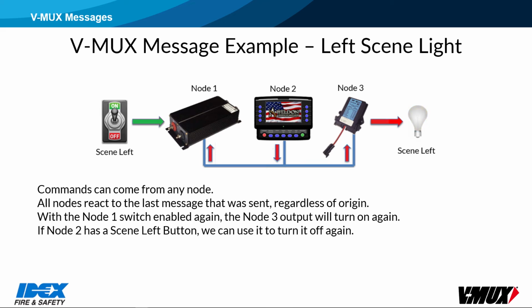Once node 2 sends the off command, all nodes will register the command as off, including node 1, which at this point still has an active switch connected to the scene left input. If the switch is turned off, the scene left command will be sent again, in an off state. Since all nodes already register that the command is off, no outputs will change.